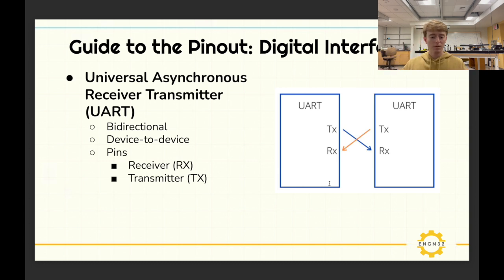So with UART, you just have to come up with a protocol for how you're going to receive all of that information and at what rate, and when the information is coming, all that stuff. You've got to decide that in your protocol. A lot of times, because now we don't have that nice clock line to keep us synchronized, I could be sending or transmitting data at any time. So I need to know the rate, and a lot of times I'll specify some framing bits and some stop bits so that I can know where my data is, because otherwise it just looks like a stream of data continuously coming at me and I don't know what is what.